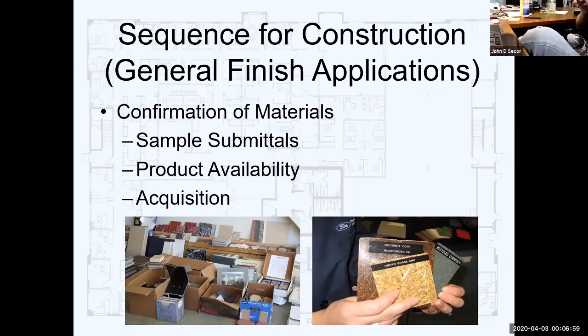So that's not a request, it's a directive put in your contract documents saying, we've got a specialty wall made of this kind of stone. I need a 4-foot by 8-foot wall section built. Now understand, it's going to cost money and the contractor is going to complain, but all you have to do is say, hey, do you really want to learn on a one-shot type of effort, or do you want to see what it looks like and make maybe some grout joint adjustments or something like that before we actually get into the full production? So that's kind of an important piece.